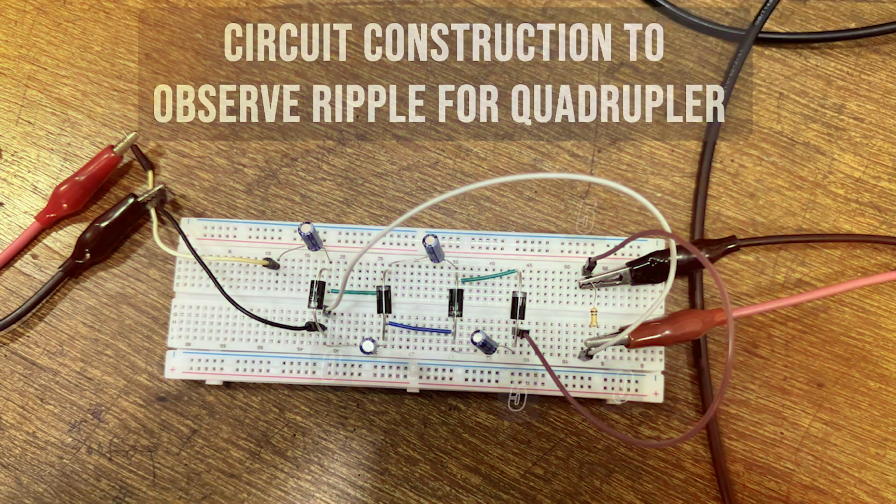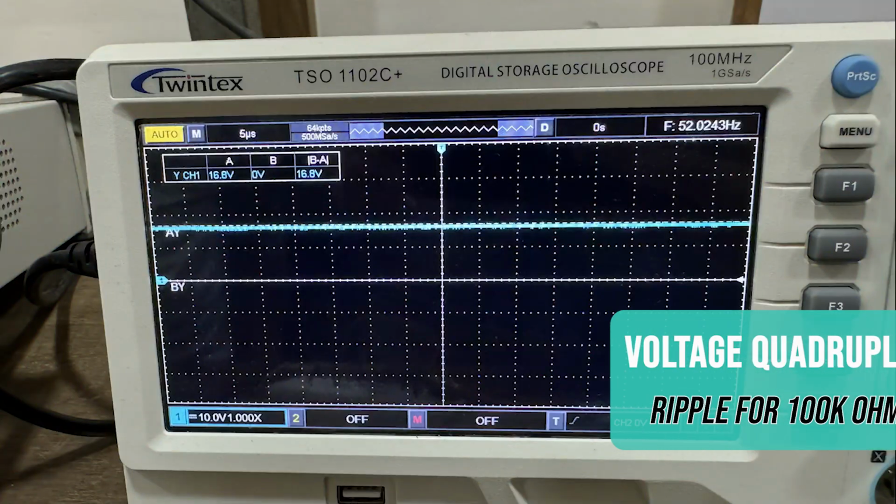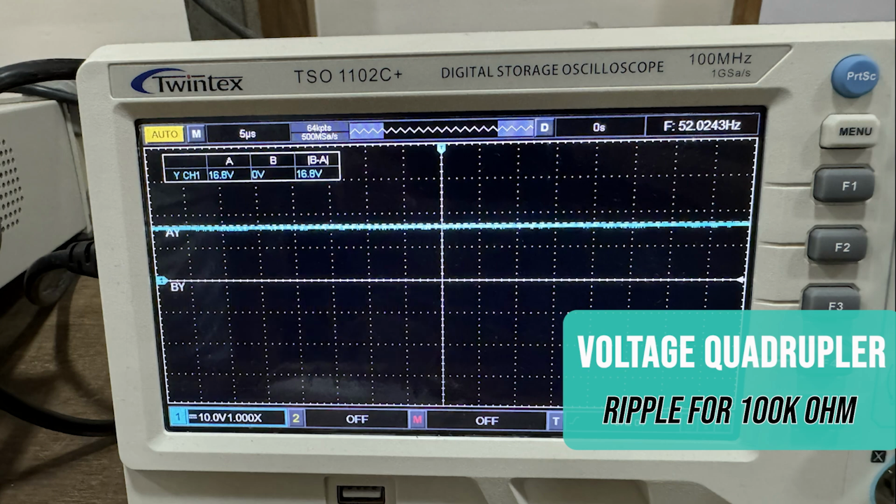Finally, the quadrupler circuit's loaded condition was constructed ensuring the load was connected parallel across the second and fourth capacitor from the input end. The output is as expected and ripple is again low to none due to high value of resistance.